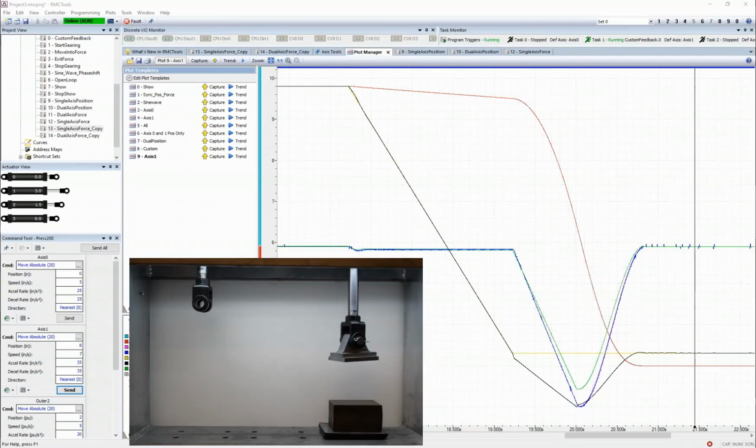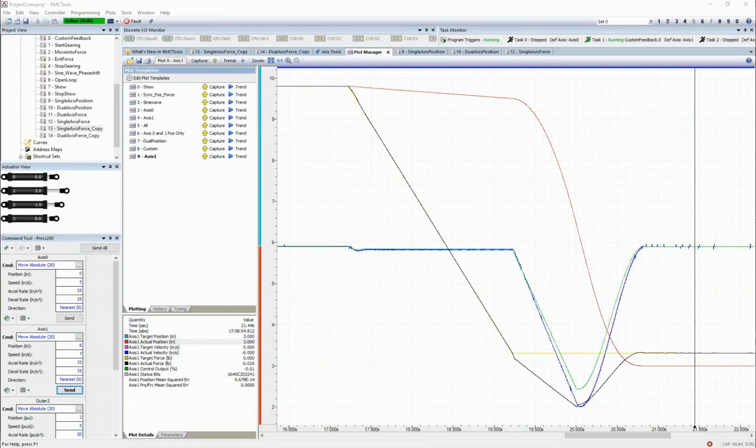Okay, so we're in position control, going quickly. We slow down. You see how much that slowed down there. We press to our 1,000 pounds. It's a little bit difficult to see it here. You can kind of see those rubber plates at the bottom are flexing a bit, but we slowly intensify up to 1,500 pounds. Go to 0 pounds, and now we retract quickly up to where we need to be.